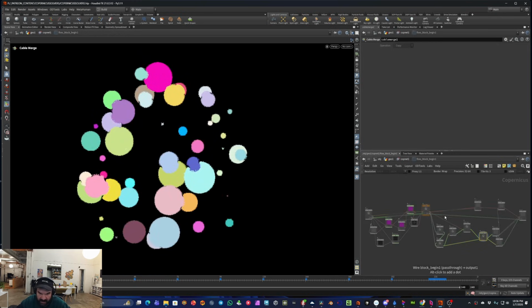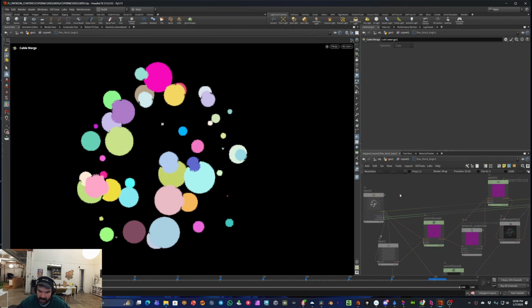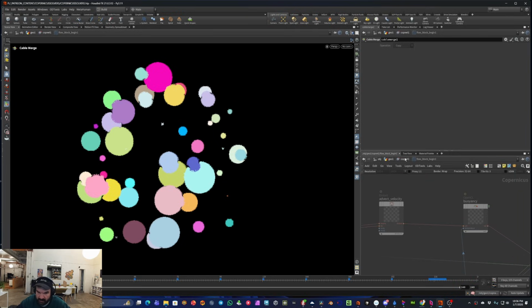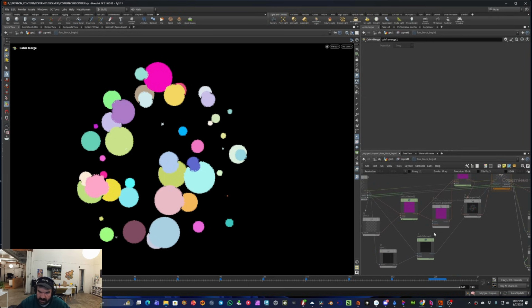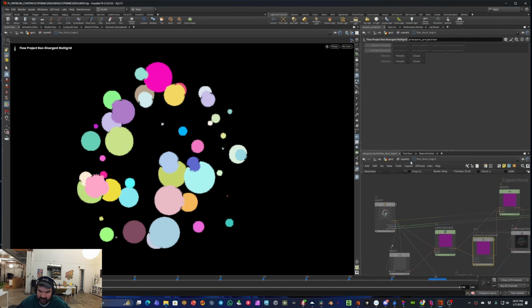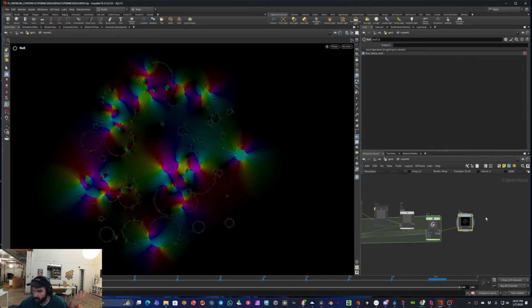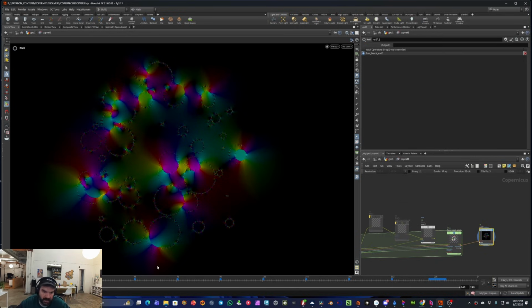And again, you can dive back in here and see everything that's going on, and it is essentially a 2D version of a fluid sim, where they're doing all the same kind of things with the project non-divergent, pressure projection stuff, and it's just running the same things every frame, just like in normal Houdini or in DOPS, but this is in purely 2D using Copernicus.